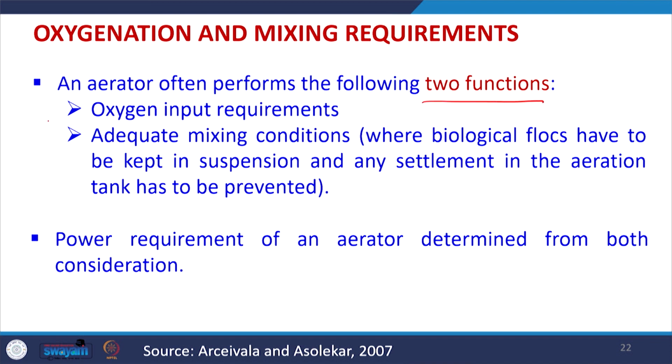One is the oxygen input requirement, and the second is mixing conditions, adequate mixing, where biological flocs have to be kept in suspension and any settlement in the aeration tank has to be prevented. So, in the biological reactors we wish to have oxygen input and also adequate mixing.